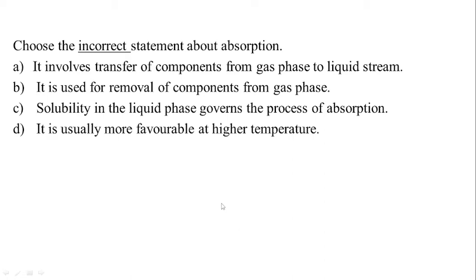Now there is one more thing. Ideally, for all practical purposes, we will be treating the condenser as one equilibrium stage. That means the vapor present is in equilibrium with the condensed liquid. That's the correct way to say this. So in a flooded condenser also, initially the vapor would condense to a saturated liquid at its bubble point, and as it goes out, before coming in contact with the lower tubes, it gets subcooled and leaves.